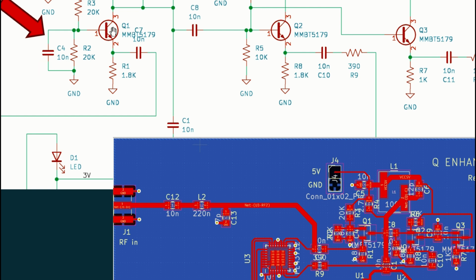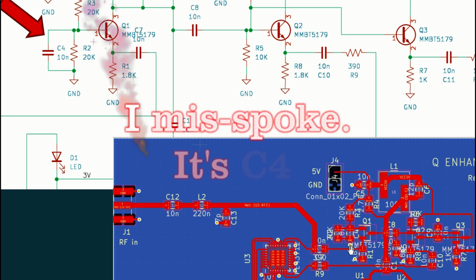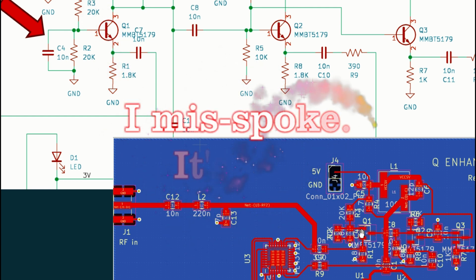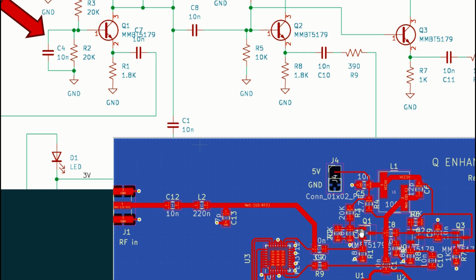Q1, the amplifier, in the layout is down here on the right bottom, and you'll notice that this is the emitter, this is the collector, top terminal here is the base, and that goes over to C1, which then goes to a via to the backside. So you'll notice that the length, the distance from the base terminal of the transistor through the capacitor over to that via and down through the via to the backside is the length we care about. And I've minimized it by putting this capacitor here.